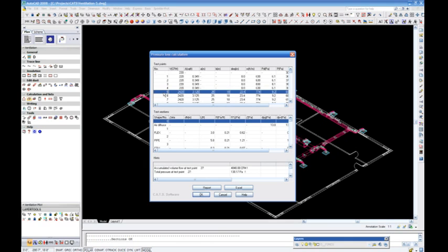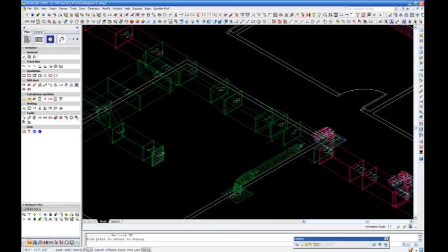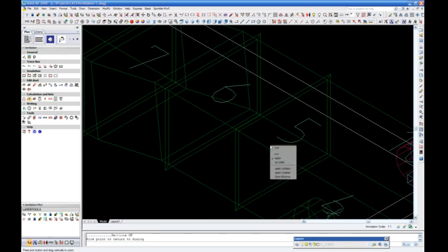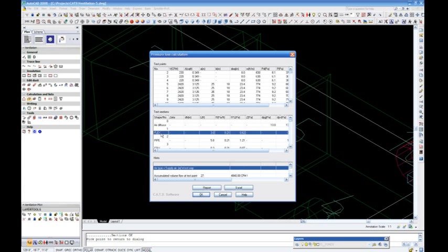By choosing a section of our supply air pressure drop calculation, the selected section will be zoomed in. Any changes or modifications to this section may be made at this time. For example, should a branch from the supply air main duct have an excessive pressure drop, this type of connection could be modified.